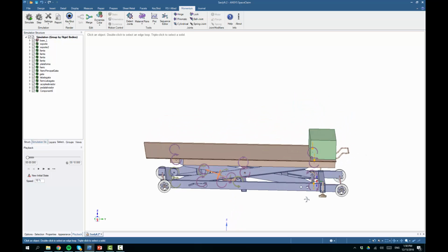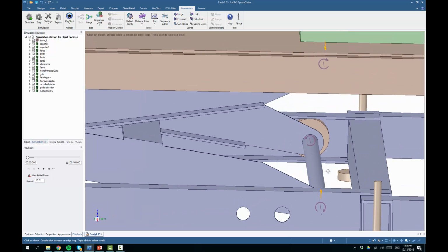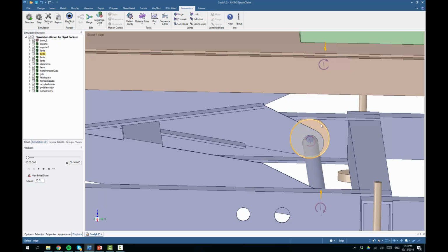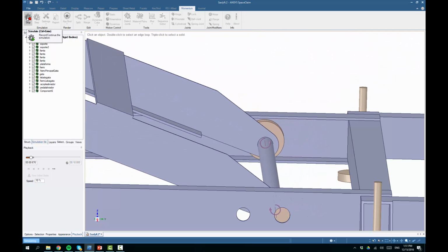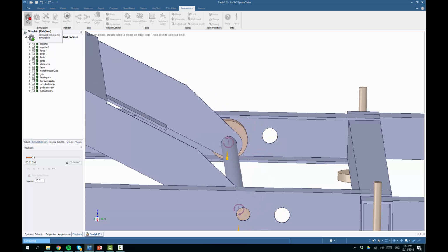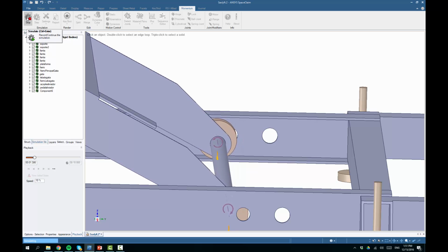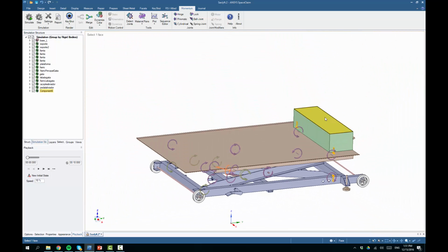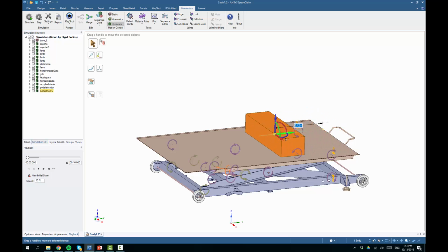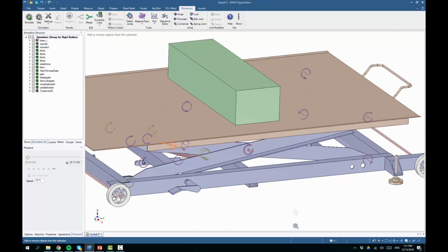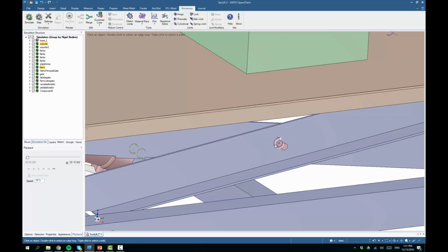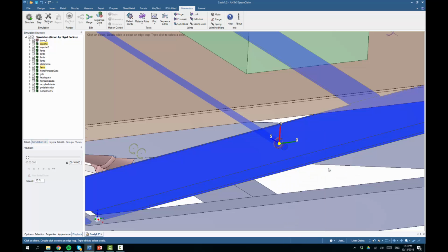We can look a little more closely at these rollers to see what's going on there. So now we're watching this in slow motion, and in the initial position here, the rollers are being pushed up against the upper limit, and press simulate. We see that it bounces up and down a little bit, and then eventually drops down to the lower track, and it also bounces when the hydraulic cylinder reaches the end of its range, which causes a mechanical impact that runs through the system. We can grab this body and move it to any place we like for the next simulation. But let's also have a look at one of these constraints to see what loads it is subjected to during this sequence.